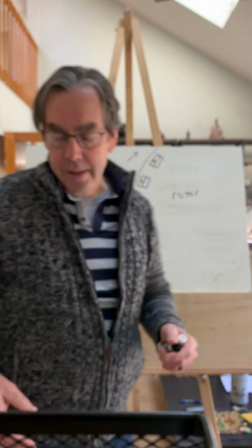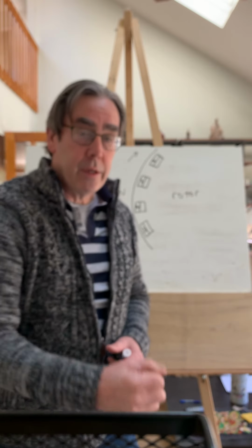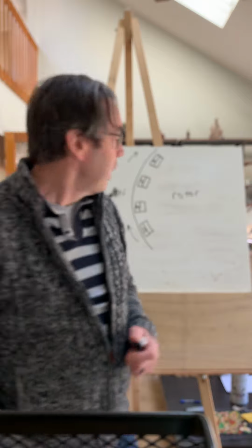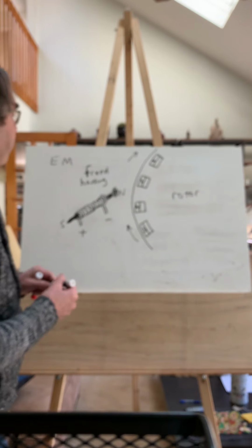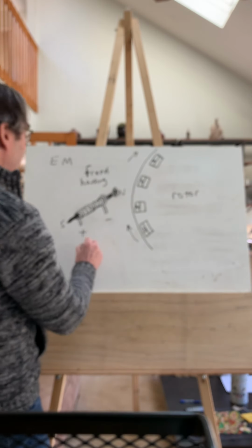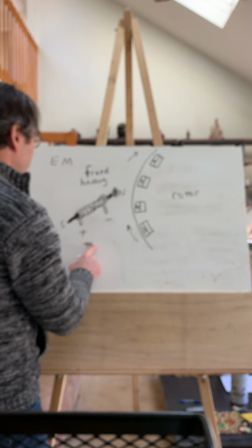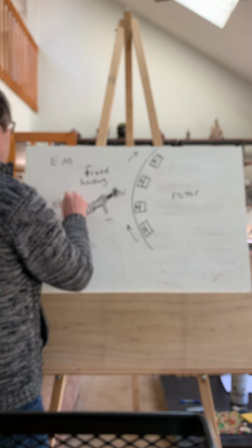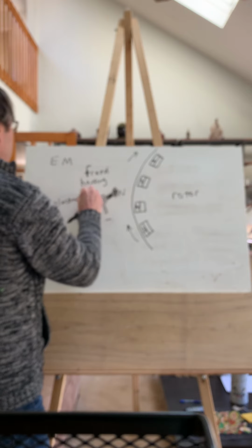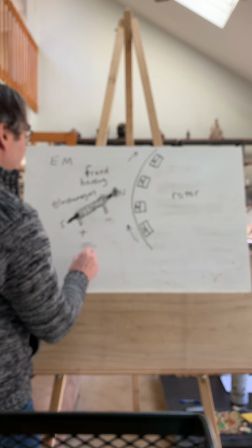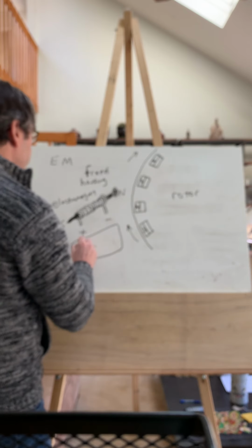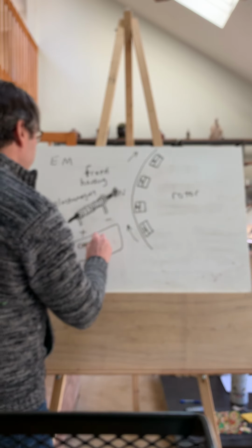And the fixed housing is like the ground the guy stands on; you can't apply that force if you don't have a fixed position to do it from. So we fix this to the housing. And then we have an electromagnet. And then finally we have a device here, which is key, which is called a commutator.